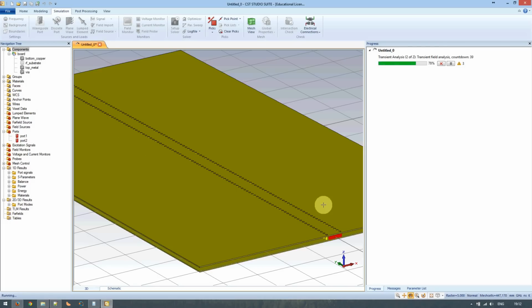The frequency domain solver uses a phasor-based technique, but it has to do many frequency samples. So particularly if you're doing wideband applications and non-resonant kind of stuff, it does take longer, and it is better to use the transient solver. And if you want to obviously verify the response of your waveguide structures over the cutoff region, you should use the frequency domain solver.